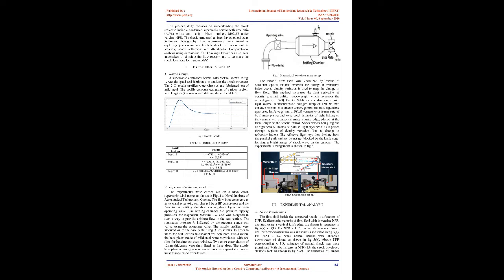The existence of a particular type of flow separation depends on the type of shock structure generated within the nozzle, which in turn is attributed to the type of profile and nozzle pressure ratio, NPR, and it has been experimentally proven that the NPR corresponding to transition from RSS to FSS and its hysteresis creates asymmetric pressure distribution on the nozzle walls, leading to asymmetric side loads which can even damage the nozzle hardware.